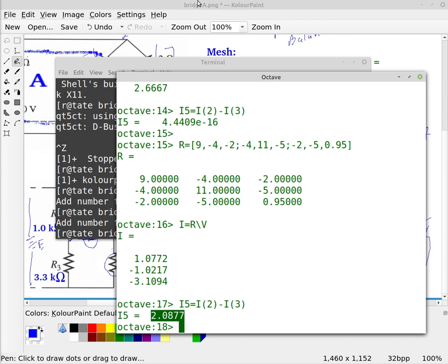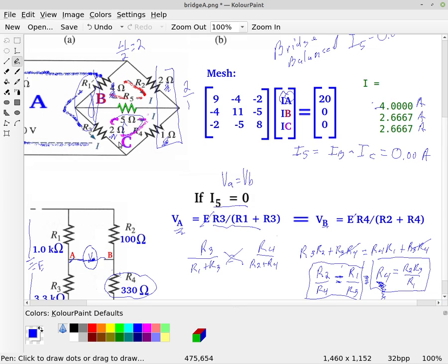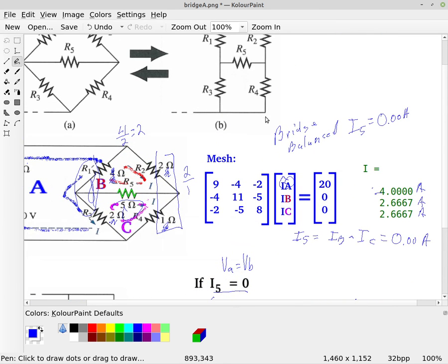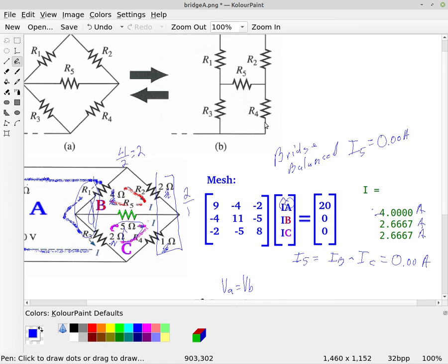So this bridge circuit is very good for measuring values, and so like I say, we use this a lot in analog sensors to measure various different parameters out there, whether we're measuring a resistance, pressure, or a force. All right, so it's a very handy circuit, very common circuit, and this is called the bridge circuit. Traditionally, it's been given credit for Sir Charles Wheatstone, who was the first one who at least published a paper about it. So you're going to be seeing a lot of this as you go through your various classes.